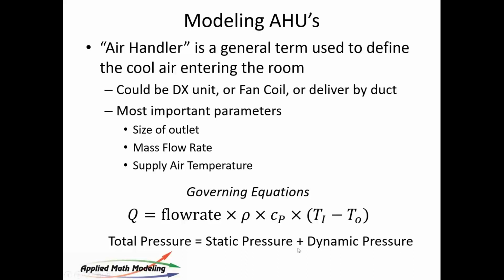What I mean by this is that these trade off for one another. If you have velocity in the air, so you have fast-moving air, your static pressure is going to drop. The relationship of these two components, as they trade off against one another, is very important in data center design because it is static pressure that allows air to get to where it needs to go.